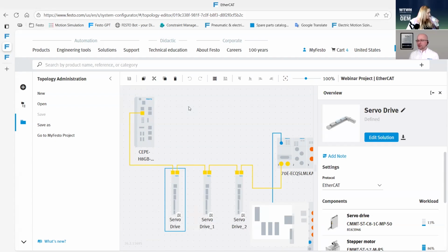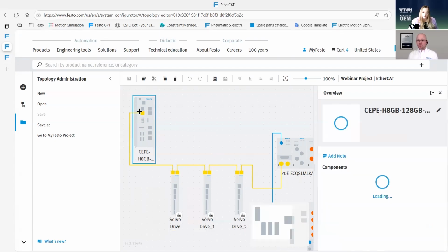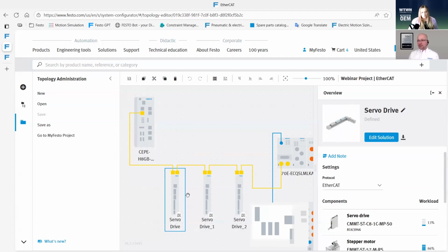Yes. And so actually there are 4 field buses that we support for basically every device we have. Well, not our controllers. Our controllers are always EtherCAT masters. That's pretty typical that the controller is locked in. But our devices, for example, these can be EtherCAT, Profinet, Ethernet IP, or Modbus TCP.